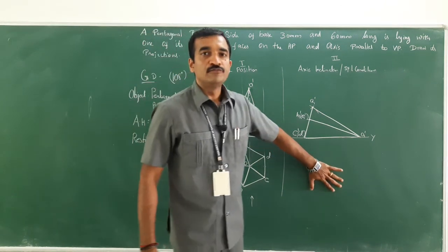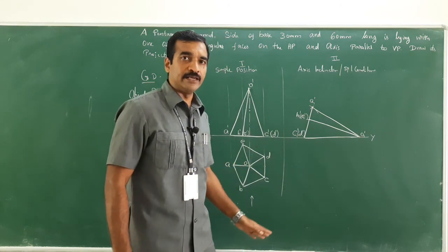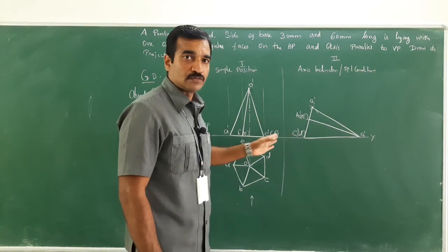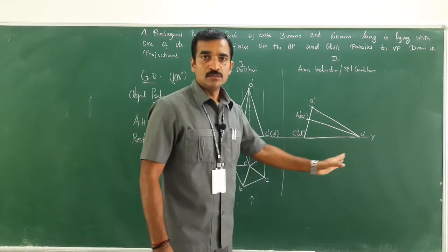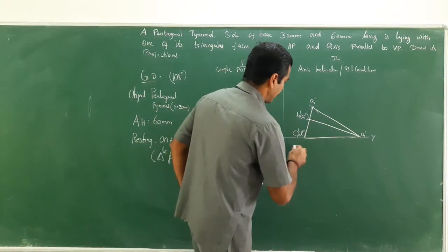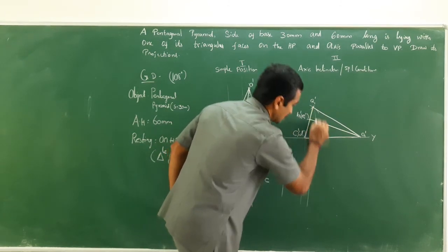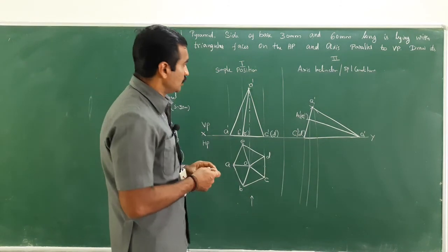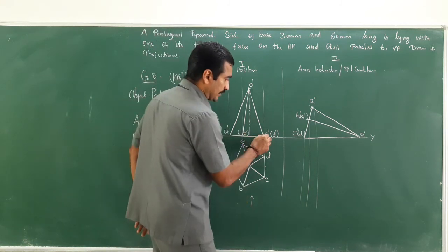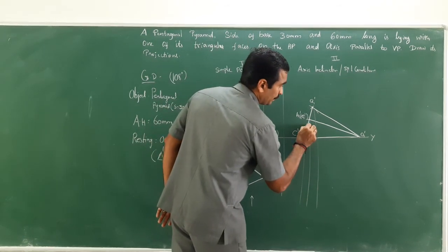Now, the final top view. How can that be drawn? By simply extending the projectors, from the front view as well as from the top view. Right? So now I'll have to draw the projectors. Before that, there is an axis, right? So this axis also you just transform here. Measure it from C to the axis and connect it. So now draw the axis.